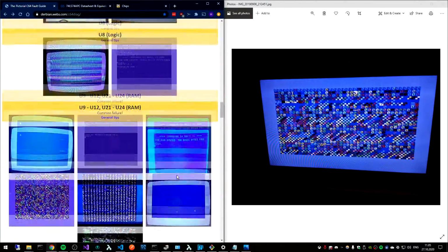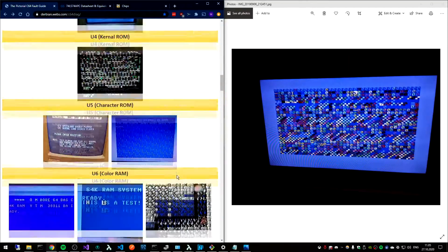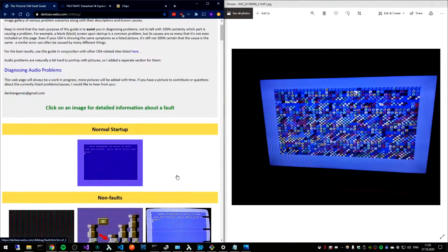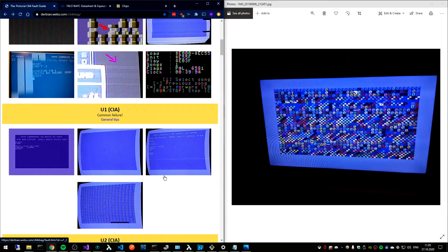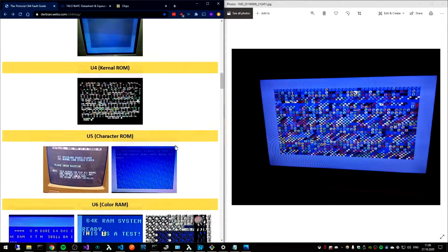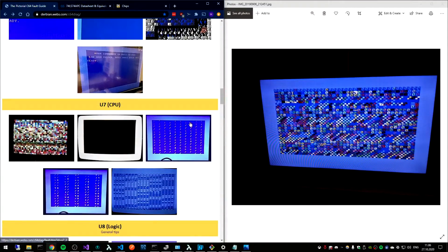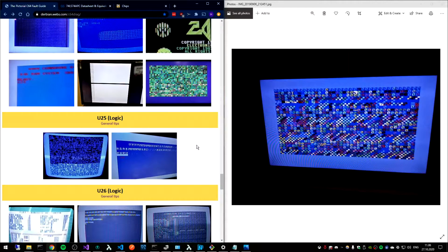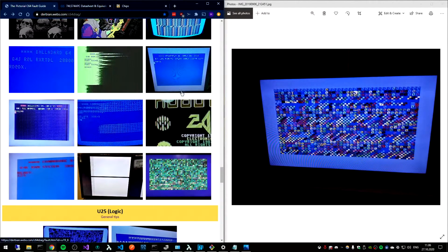But I definitely did Google a lot, and didn't really figure out what issue that might be. All I had to go on was the RAM. When there's something wrong with the RAM, you usually get some picture on the screen. The video signal should still be working even though the RAM is faulty. You just get a garbled screen.